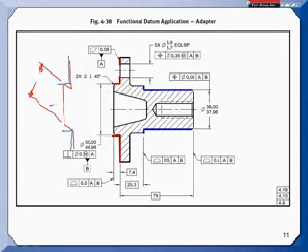So I will get a datum axis that looks something like that. Great. And that's not the issue. The issue is the mating part. Exactly. So it really comes down to functionality. The reason you put the perpendicularity on here is that I want it to go together. Yep. Okay. Great.